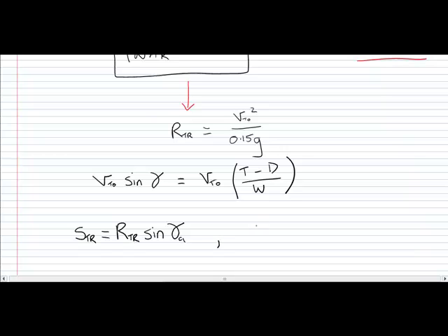And the height that the aircraft will have climbed through during this transition phase, we'll call this H_TR. Now this starts becoming important in making sure that your aircraft can actually work its way above the obstacle, which in the case of the aircraft you're designing is at 500 meters.